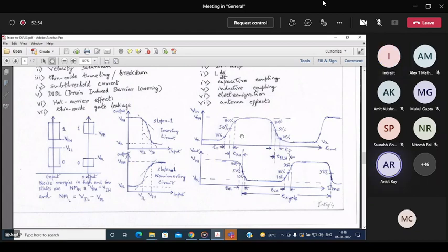So when you are talking about the output of a device, at the output side, always the voltage levels will be thought about in terms of VOH and VOL. VOH and VOL assume importance whenever you are talking about the levels of voltages, be it at the input side or output side. Say VOH, that means we are talking about plus 5 volt, 0 volt.